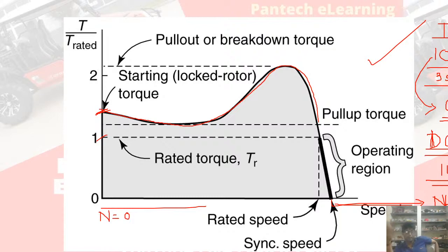To avoid this kind of thing, as well as because continuous hot starts may deteriorate the basic insulation level of the stator winding, for medium voltage machines it is recommended by the manufacturer that a successive 3 hot starts is permitted.